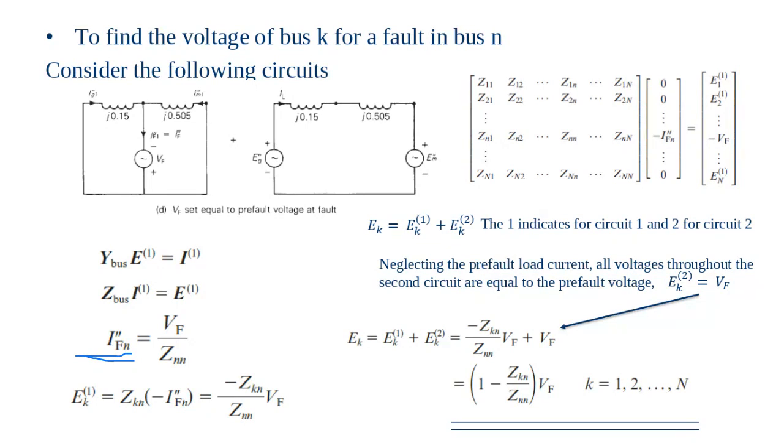Okay, open and closes. Then also from the fault current, what is the advantage? Here we can set the circuit breaker limit. When will the circuit breaker open? And also the specification of the circuit breakers. Therefore, we need to calculate the fault current.